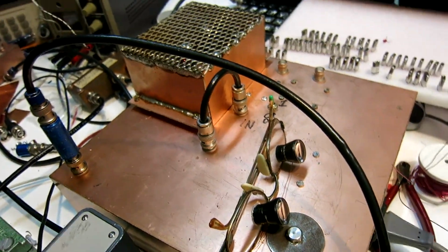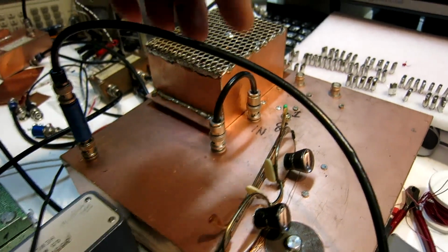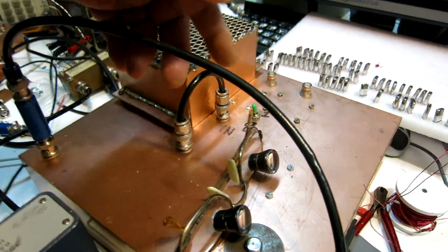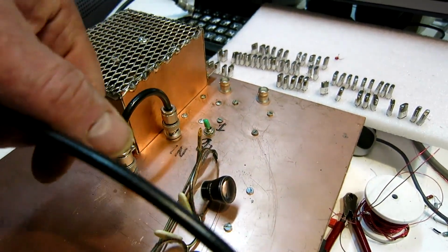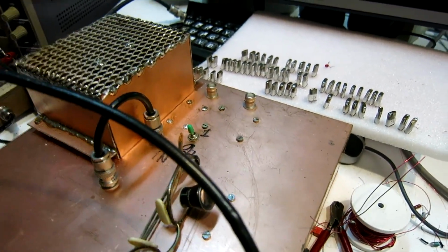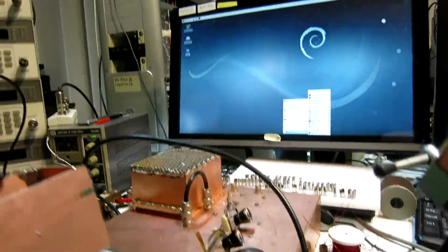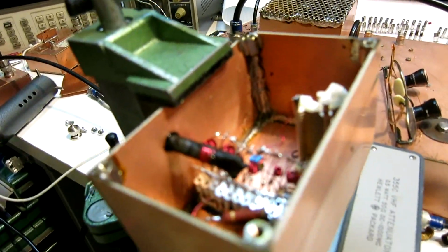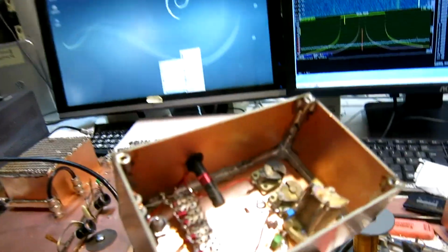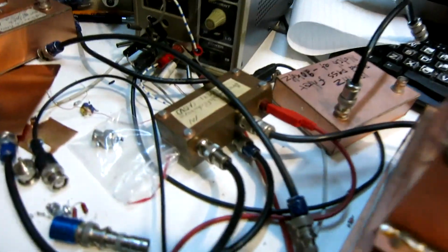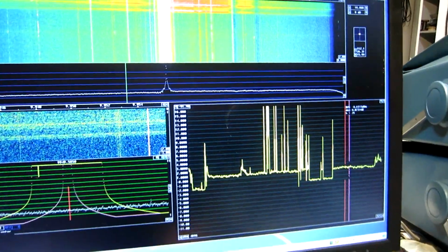I'm running the vacuum tube amplifier as an oscillator. Output input, this is the limited output. And the switch is set for the 2-section crystal filter. A 3 dB attenuator and then the stepped attenuator. Into the selective load, a quarter wave cable, and then the notch. And after that, the low noise amplifier here. And this is what I see on the spectrum analyzer.